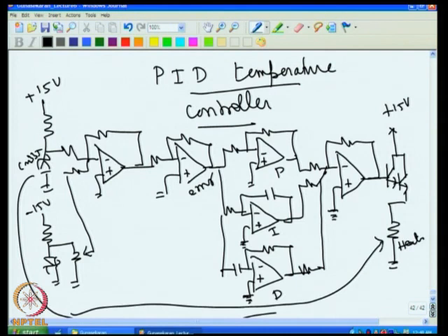This is physically kept here. This is driving the oven, and that sensor is connected here, so that it acts as a temperature controller, because that feedback automatically takes place as temperature sensing is done. That's how the feedback is taking place, and then the system will try to stabilize at the set value. That is the aim of this PID controller.